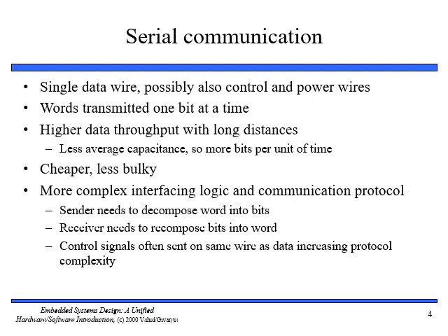When data is sent, the sender first transmits a bit called the start bit. A start bit merely signals the receiver to wake up and start receiving data. The start bit is then followed by n bits of data. So initially we send a start bit, and the start bit wakes up the receiver, and then we send n bits of data, where n is the size of the word, and a stop bit. The stop bit signals to the receiver the end of transmission.